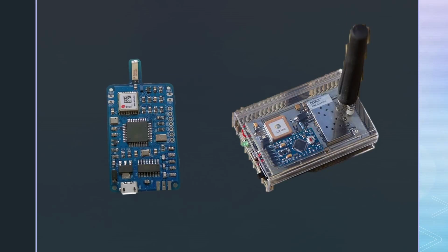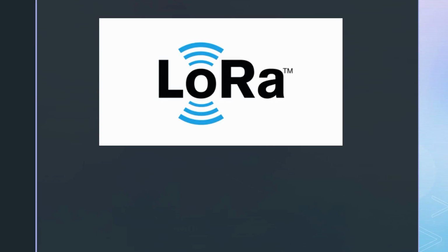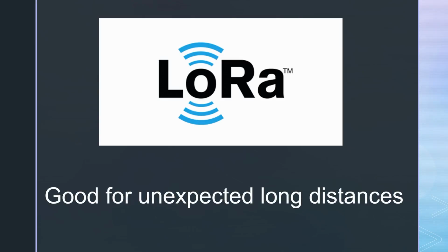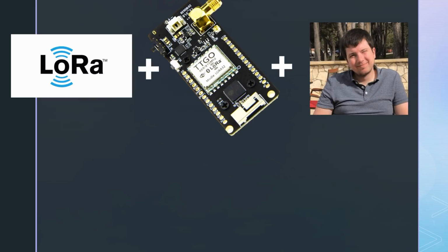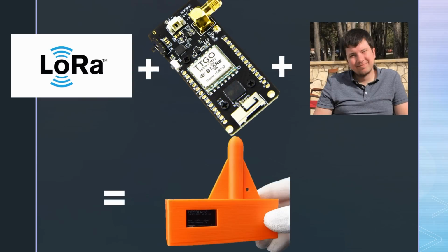You might know APRS location trackers on 144 MHz. And you might have heard of LoRa, a relatively new modulation standard capable of bridging unexpected long distances at low power. Combined with cheap hardware and an innovative Austrian project, gets us an exciting mix: LoRa APRS trackers.